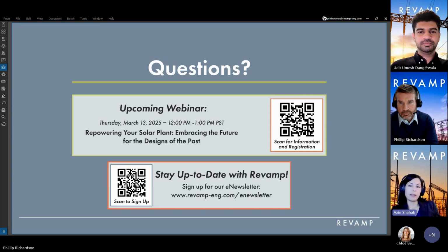And then there are some other studies that are a little more specialized, such as TOV or grounding. So to answer your question on where an entry-level study engineer should get started, I would say on the more general studies, such as load flow, thermal, short circuit. Thanks, Azim.